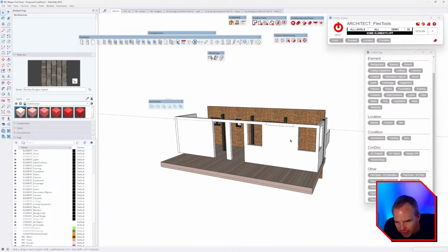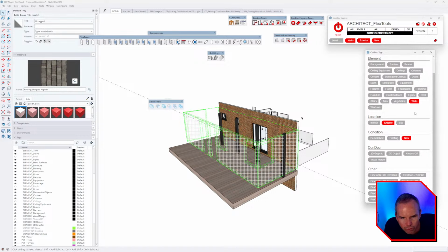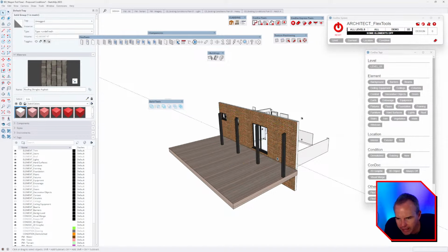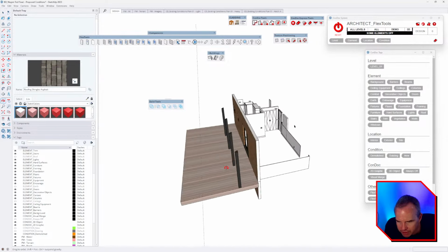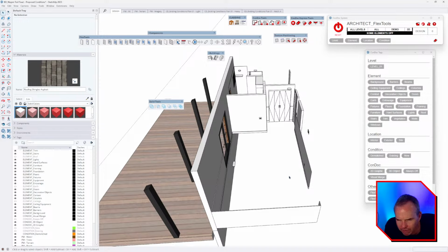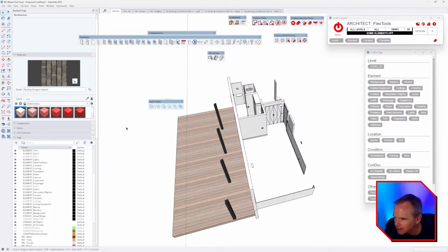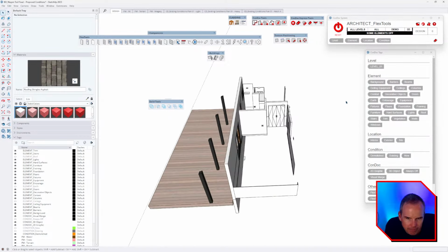And this is a great way to check for things that are untagged or not properly tagged. Like this, I can tell right away, this is exterior, new walls, level 1. All right, so now this is everything that's being demolished. And let's make sure that we have interior and exterior. So floor wise, what's up with our floor? So I can see, I guess we're not demolishing any floor. Okay, we're good. All right, so then you've got existing and new.